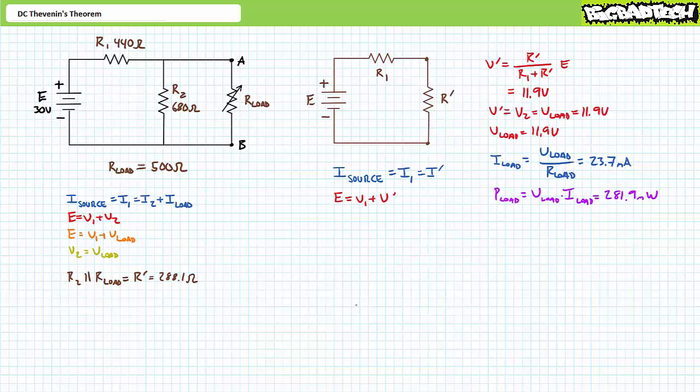This being said, here are some reliable tools that will help you out. Kirchhoff's voltage law and Kirchhoff's current law. Never, ever attempt to analyze a circuit without first having performed a thorough Kirchhoff's voltage law and Kirchhoff's current law analysis. Application of fundamental series and parallel properties can assist you in visualizing how current flows through and how voltage is apportioned in a particular circuit, and allow powerful simplifications to be made.